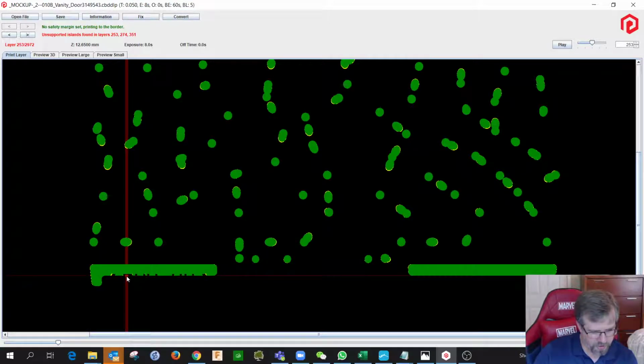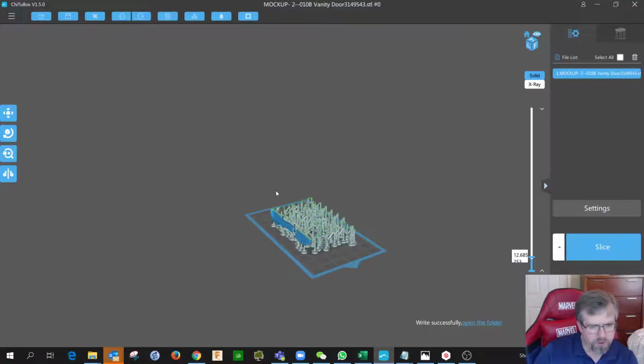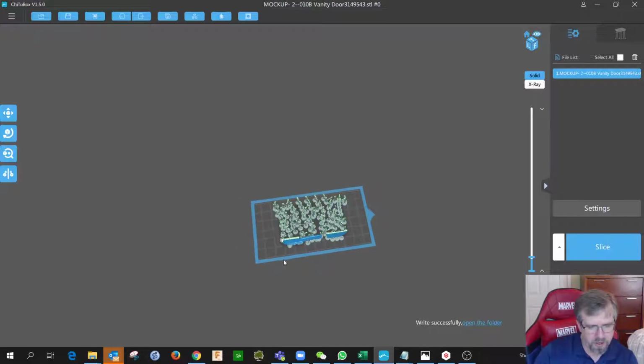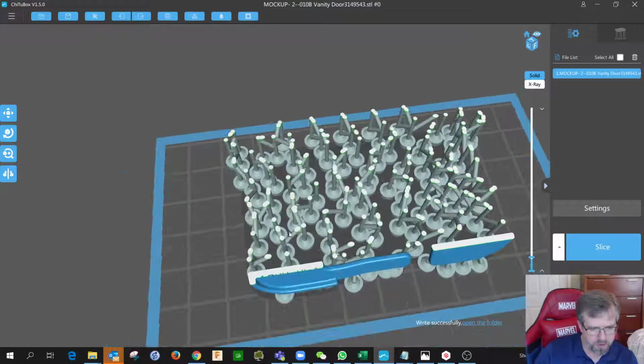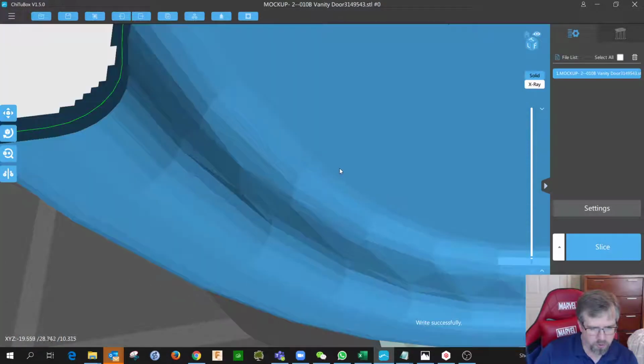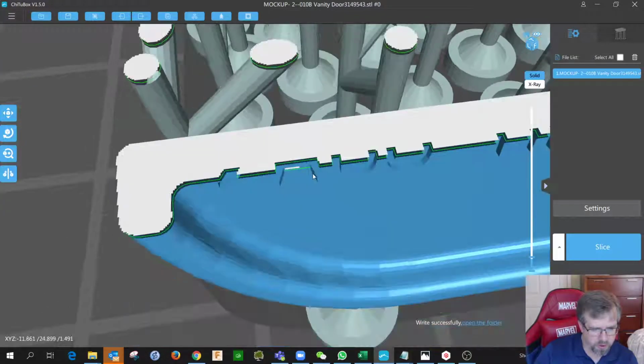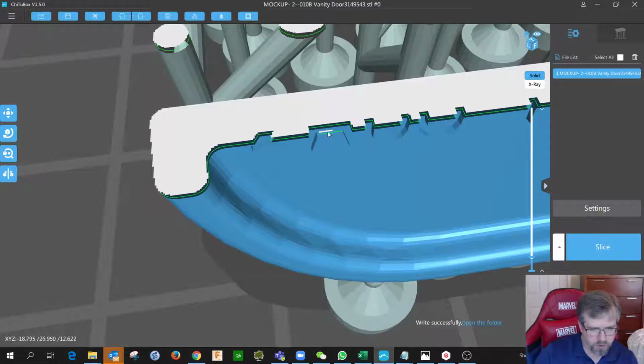And actually what I think that might be is there's some inscribed text on this object. And let's go try to find that. So it has like kind of like these highlight bars in kind of a reddish color that show you where our issue is, and they're bright red where the unsupported patch is, or the island. So now if I go to 253, which I'm at, and I zoom into that area, lo and behold, here is our little unsupported island.